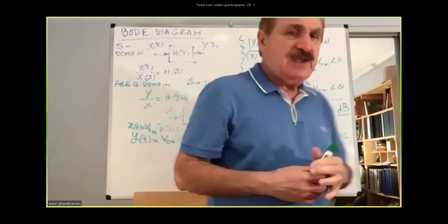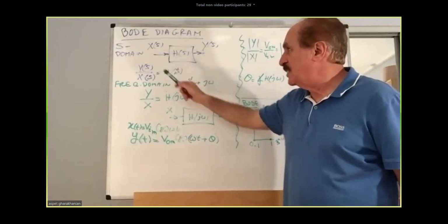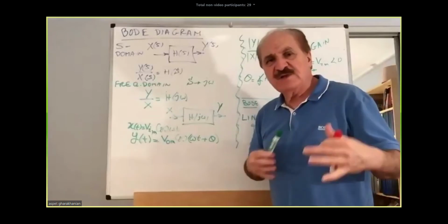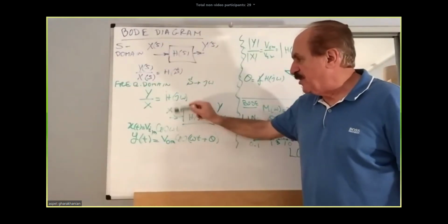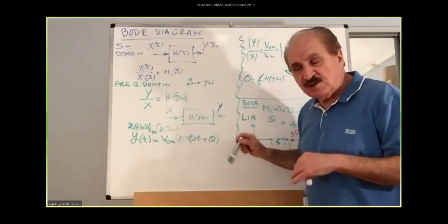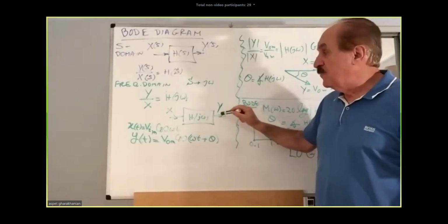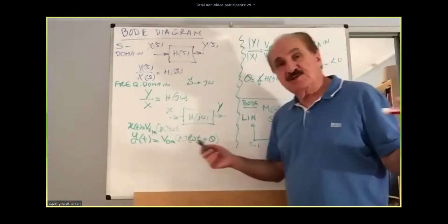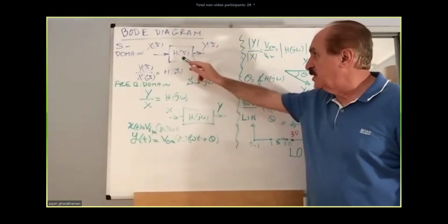I explained the transfer function, our traditional, which is output Laplace over input Laplace. It comes always as a function. But if your waveform is a sinusoidal drive at the input, then the output is going to be a sinusoidal also at steady state when the transients expire. And that can be found, the output amplitude over input amplitude, which is gain, can be found by substituting s equal to j omega in the transfer function.